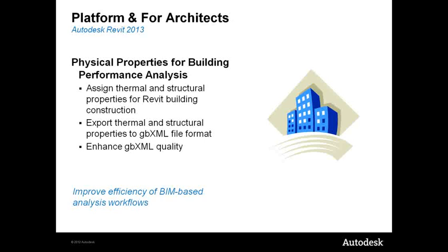When you choose to include thermal properties during export, construction thermal values defined within Revit building elements can be exported as GBXML for downstream building performance analysis applications. Bottom line is, improve efficiency of BIM-based building performance workflow with new physical properties.